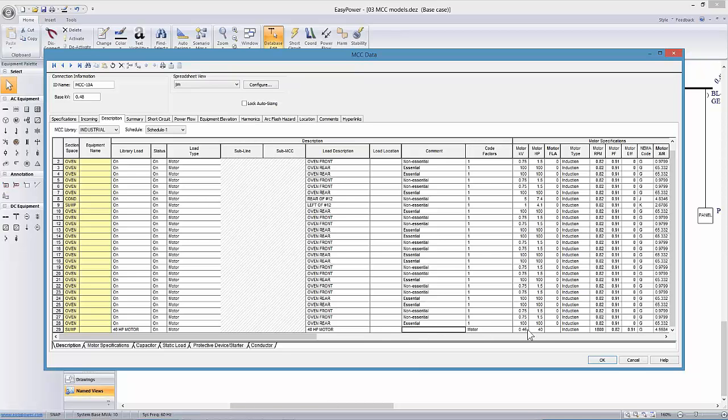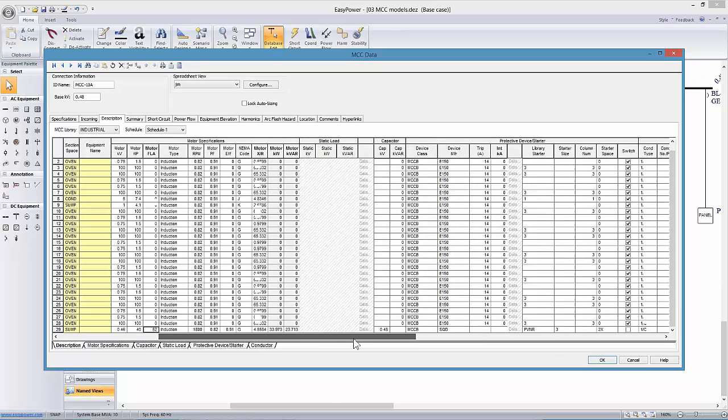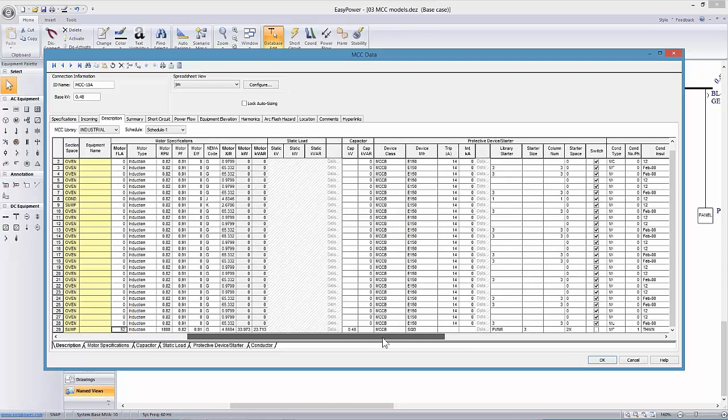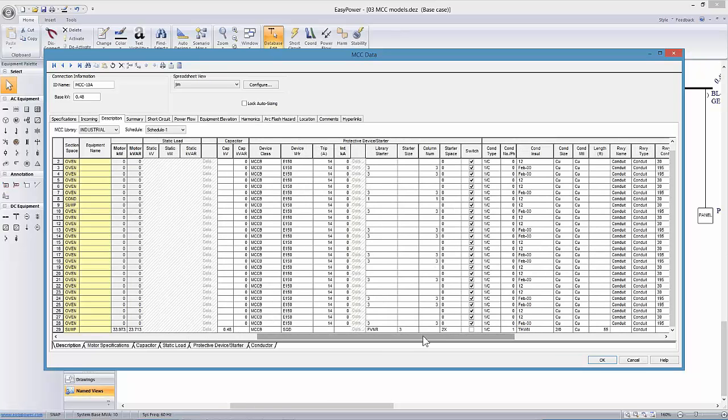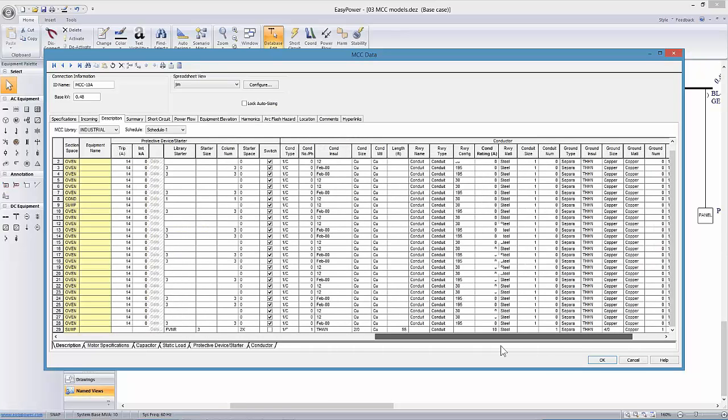and I've already got my interrupting. My full load current hasn't been designated, so I calculate that. But because I selected this with the setup of the breaker manufacturer, I should be able to carry in all the settings that I pre-configured.